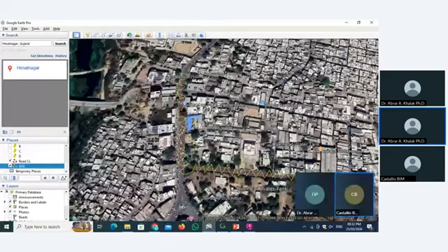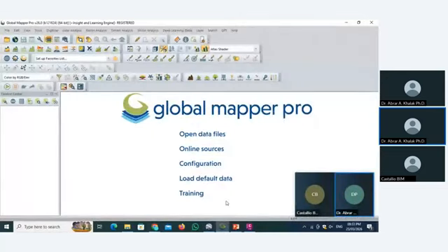Okay, so here we take two things, road center line and OGL surface. Now, see, Google Earth gives us two things, but they are not providing us an exact elevation. So if we want exact elevation for this terrain, we are going to use the Global Mapper software. So now let's start the Global Mapper software. This is the main interface of the Global Mapper software.